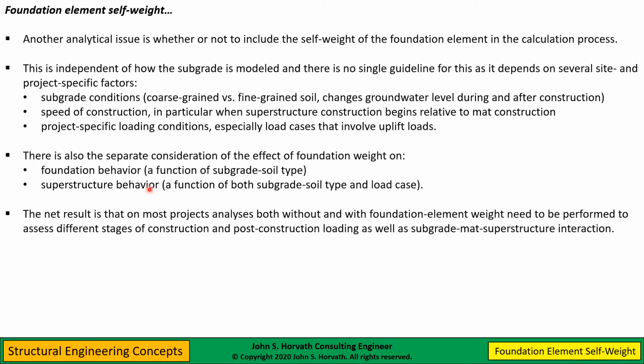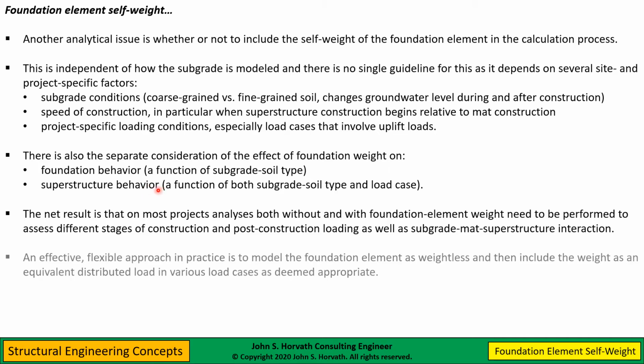You need to consider different stages of construction and post-construction loading. So the answer, as I said, is there is no single answer. One way I found flexible when you're doing an analysis is you input the foundation element as weightless, and then you can actually include the weight or remove it, add it, include it in a staged analysis as an equivalent distributed load as appropriate.